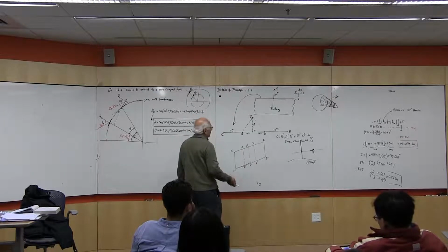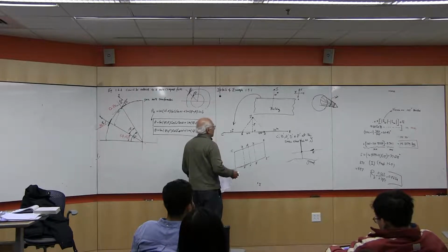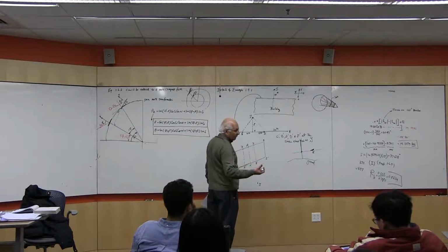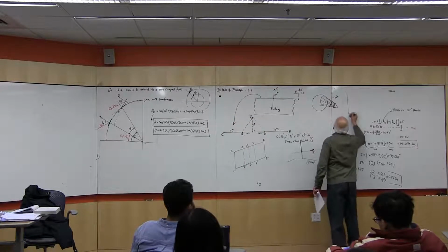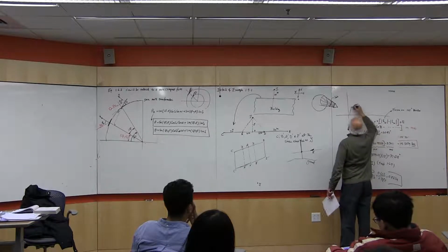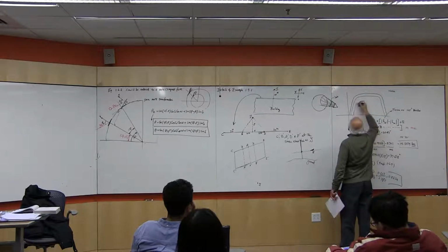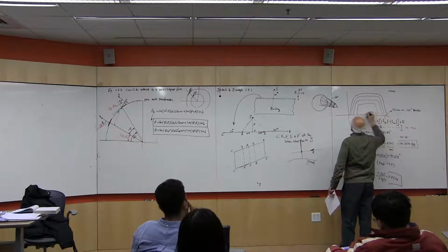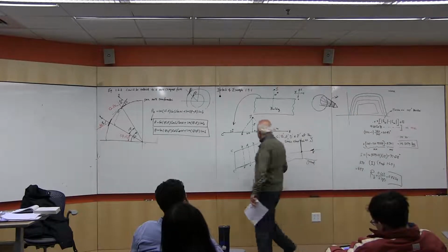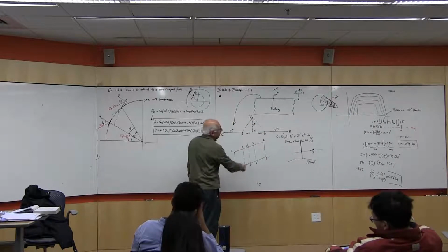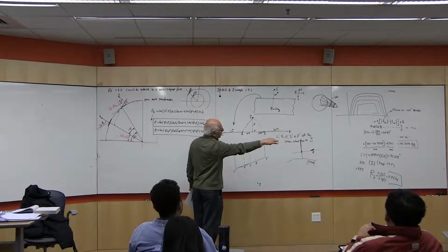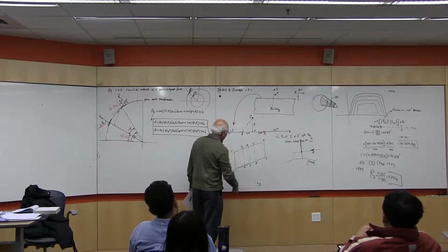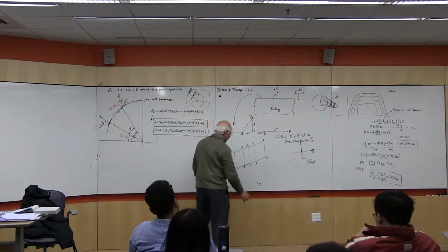All right, so the idea is that we calculate a bunch of alphas and gammas, alpha S's and gamma S's, so having the sun charts for that location, if I can find the corresponding values of these angles, gammas and alphas, and put it there, then I can draw a fitted line through that and then find the shadow and determine whether this is a good location or not.